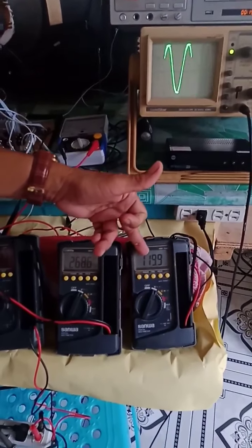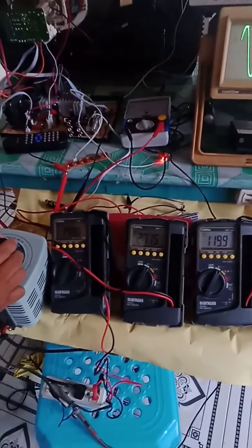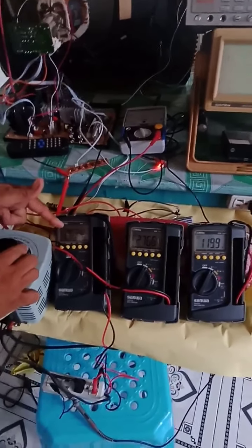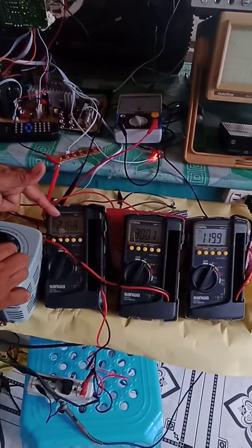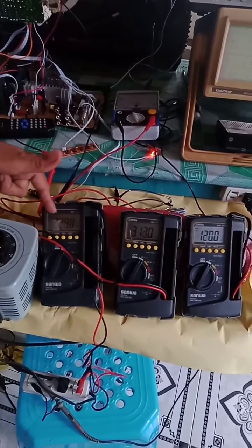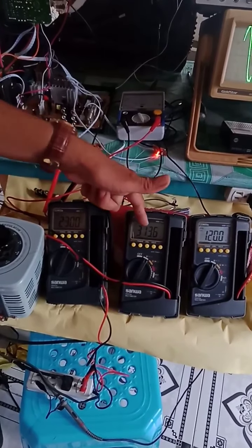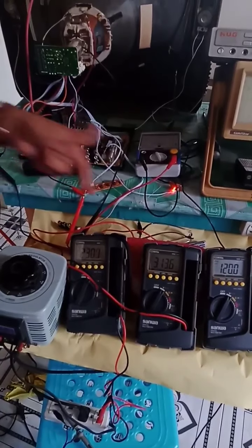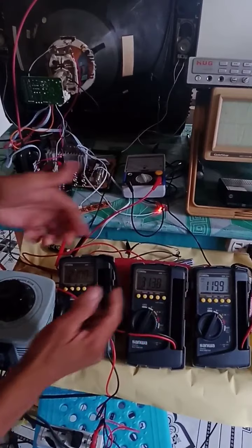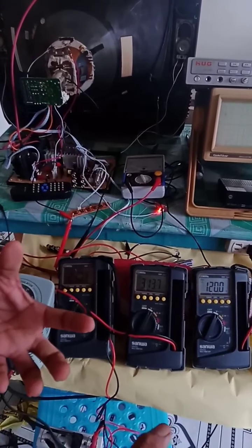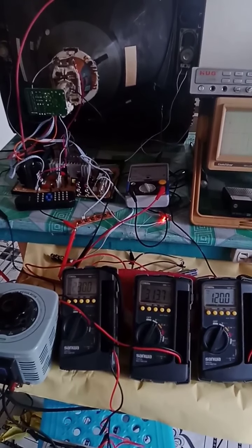It retains the same, even if you increase it higher. Now we are increasing the AC voltage of the TV receiver to 230. Now the voltage across the capacitor is also varied to 313 volts. A while ago, that was 303 volts when the voltage at the outlet is 220.